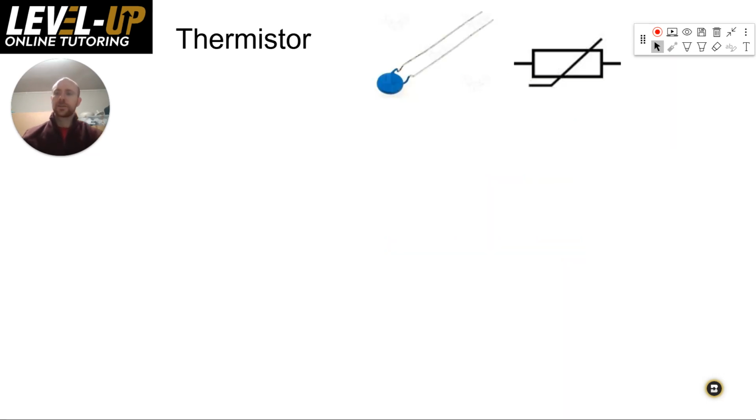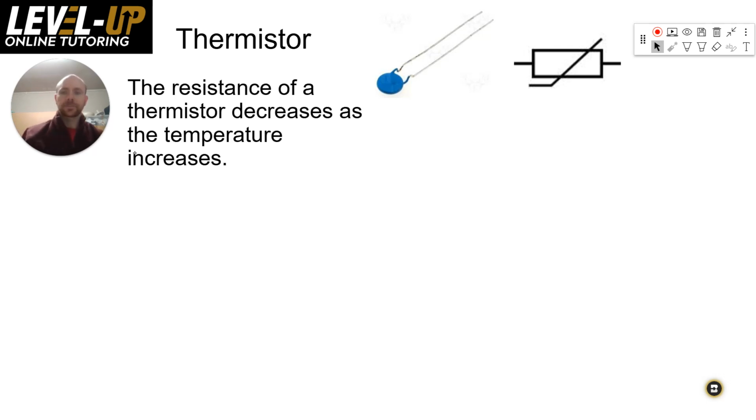Okay, the final two things we're going to look at here are thermistors and light-dependent resistors, LDRs. For these, you can't demonstrate this on the FET, but you actually need to be in a lab to do this, and you would see how the resistance actually changes with temperature. So another practical you could do would be measuring the resistance as the temperature of maybe a liquid changes.